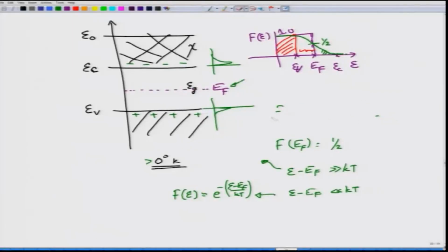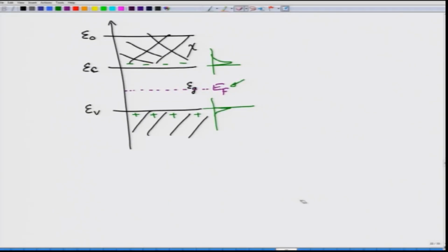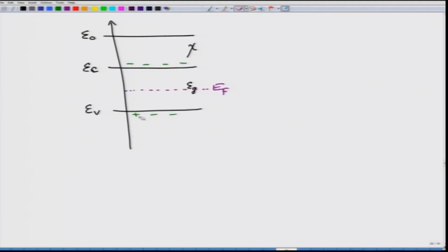Let us consider this. Suppose my dopants are all of the N type. N type means you are allowing excess electrons, and because now you have doped and the material is still in the equilibrium situation, what you find is that there are excess electrons, and when there is sufficient amount of thermal energy available, then these electrons should be easily crossing over to the conduction band and therefore must contribute to the conduction band electrons.